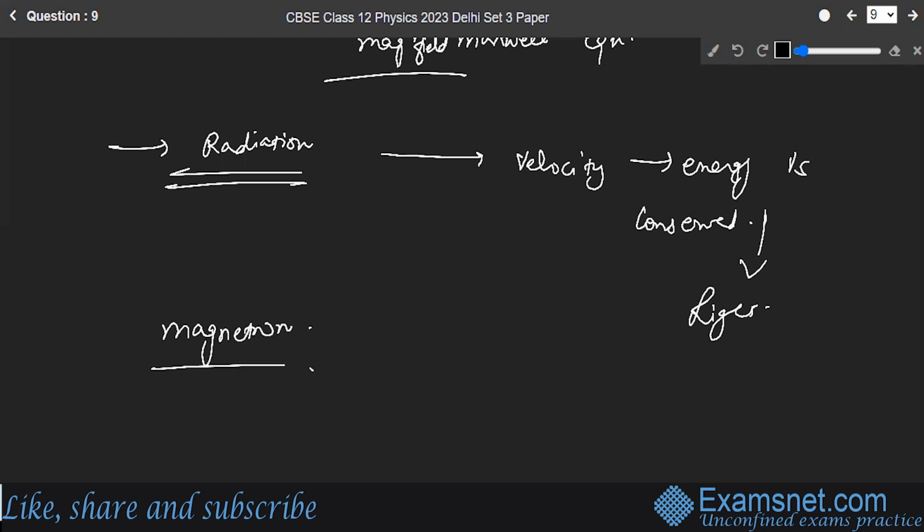Inside this magnetron is a cavity which is like a circular racetrack for the electrons. The electrons go round this circular track at immense speeds. A fluctuating magnetic field causes the electrons to wiggle back and forth towards the inside and outside of the racetrack. This wiggling happens at a very high frequency, and this causes the generation of microwaves.